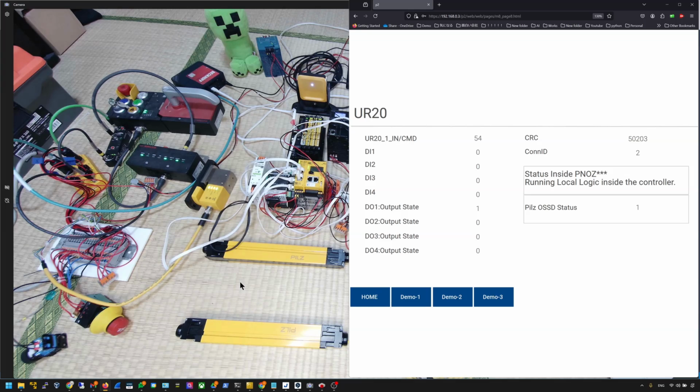Okay, great. And you can see the output will be shut down and will turn on again. But you can see there is a difference between here and here. The status is different because actually these two statuses run inside my FSoE master. So you can very flexibly define your program, have a safety relay, and add or delete logic without needing to write it all again. So that is the advantage of using safety communications.